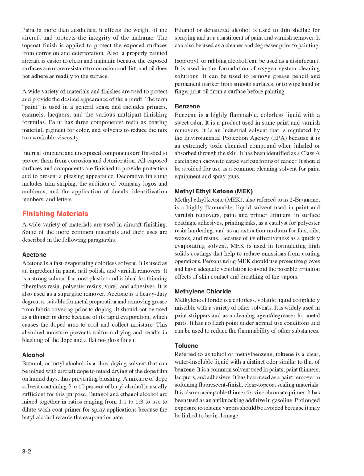A wide variety of materials and finishes are used to protect and provide the desired appearance of the aircraft. The term paint is used in a general sense and includes primers, enamels, lacquers, and the various multi-part finishing formulas. Paint has three components: resin as coating material, pigment for color, and solvents to reduce the mix to a workable viscosity.